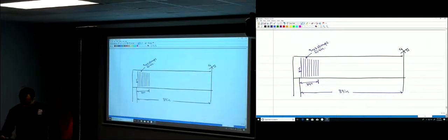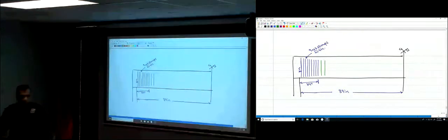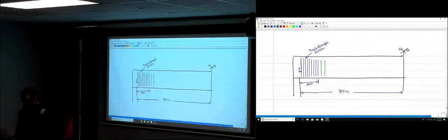Okay, 44. So the second part here, I go by a distance of 6. So how much is this? 40, and then 44. Okay, so those two here, this is 2, number 3 stirrups at 6 inches.